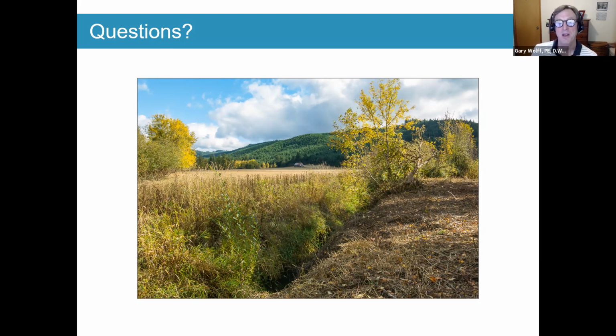the scour. And there's even some equations in there if you understand what the soil properties are and you've got very cohesive soils. If you know what the geotechnical properties of those soils are, mainly the critical shear stress, which is often a hard parameter to get at, the scour equations can take that into account. There is no easy way to account for bedrock.